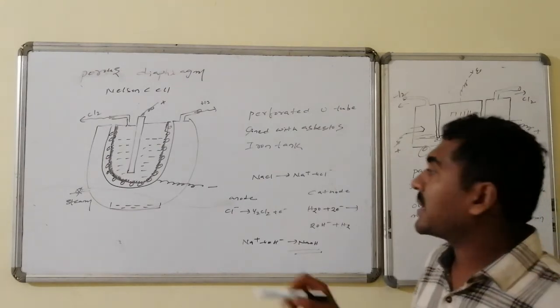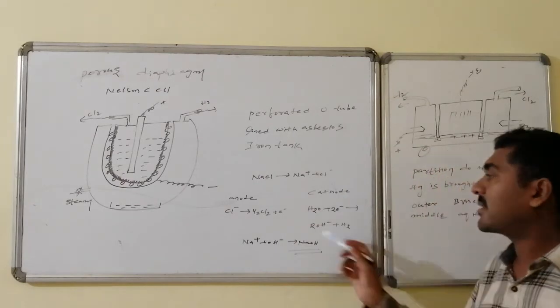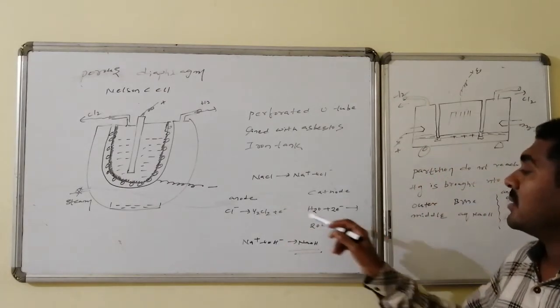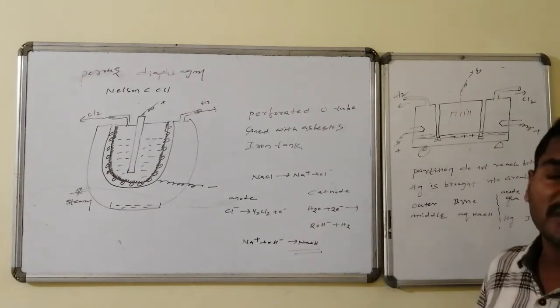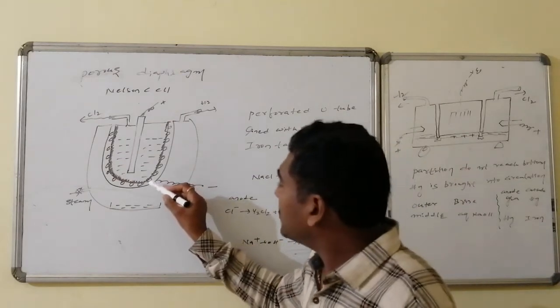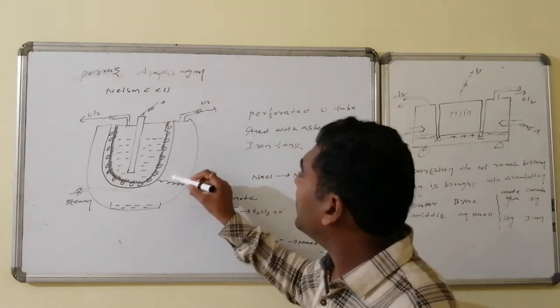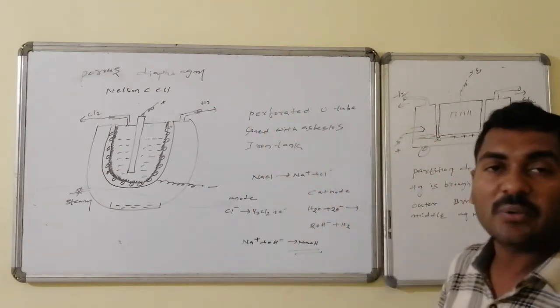Whereas at the cathode, whatever water is there reacts with the electrons given at the anode and participates in reduction at the cathode. By taking those electrons, water is preferentially converted to OH- followed by hydrogen. Through these perforated holes, the liberated hydrogen goes through the outlet.